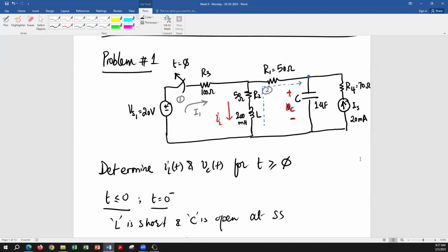Yes. I only want to know why R4. Why should I take it into account? Answer that first. So this is how I'm interpreting this as well, as the voltage that goes pointing from ground, going up, and going to the right. So we know the voltage across IL right there. But with the current though, isn't there voltage that's pushing that current up through IL and going through R4 and going to the left? Did you get to the node at which you are trying to find the voltage though? You get to the node already? Why do you want to move beyond that node, right?